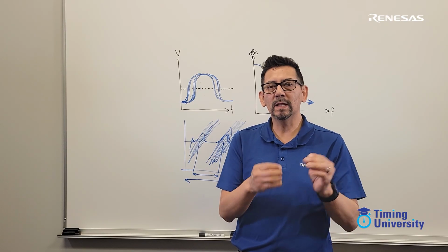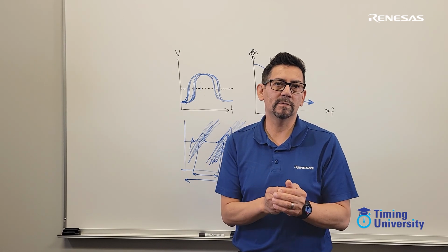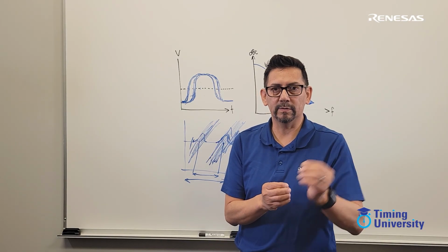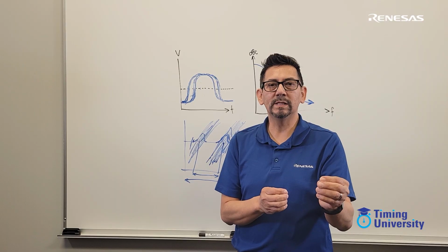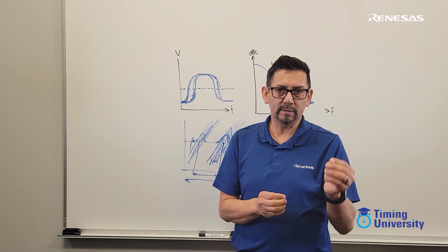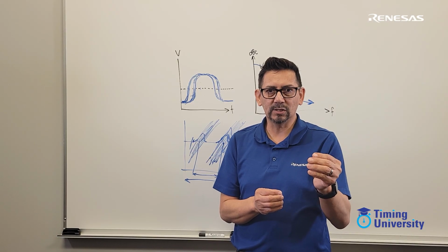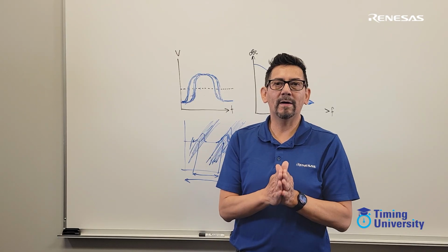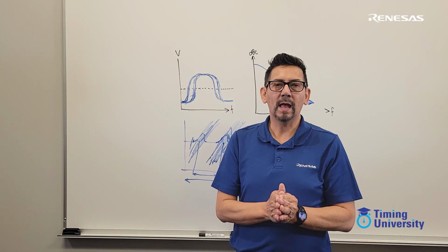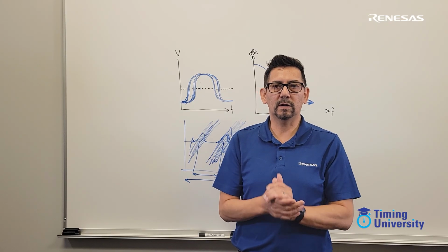At that point, you can manipulate the other chip, trying to see if you can change the spur level. For example, you can change the amplitude of the signal of the other device, or you can change the frequency of the signal of the other device. Once you make changes to the other device and you can determine that there's a correlation between that change and the spur level, that now means that you've identified what the source of the noise is. At that point, you can take a look at the layout and see where the two signals are coupling.